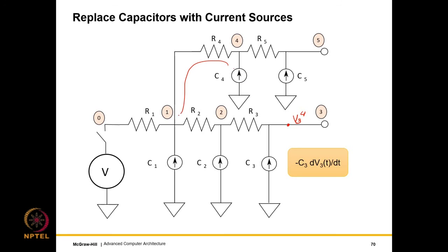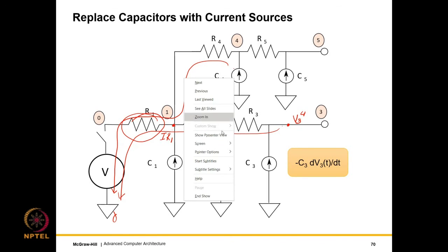Then we will have one current flowing in this direction because the rest of the currents are disconnected, and then the voltage over here will be I times R1, right? That will exactly be the same voltage over here because there is no current flow along this branch. And the important point to bear in mind is that the shared path is only this much, and this shared path in this case contains only the resistor R1.